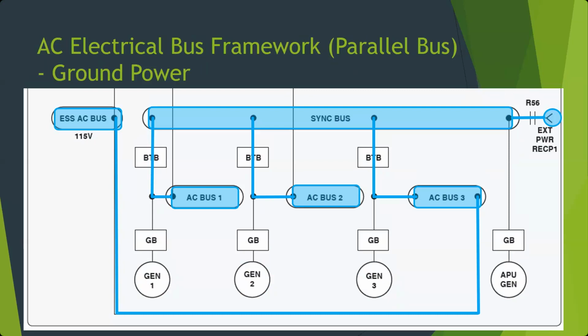At any given time, we may be running a couple hydraulic pumps. Those are some big current draw. We might be running a fuel pump or two. That's a somewhat sizable fuel draw, though it's not huge. Maybe some lights sometimes. Honestly, the landing lights are a big current draw, big old school light bulbs that when you stand in front of them, you get a suntan and you can feel the heat coming off of them.